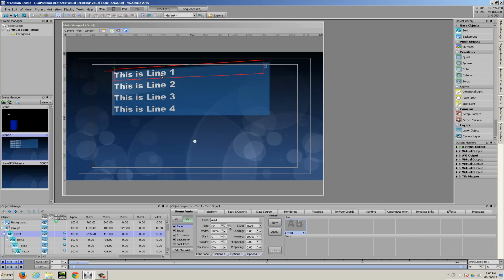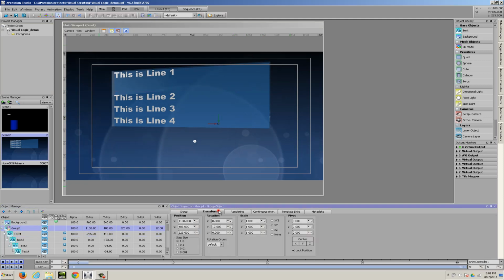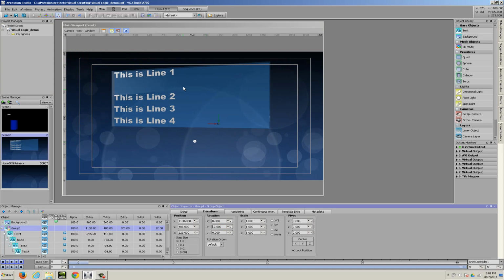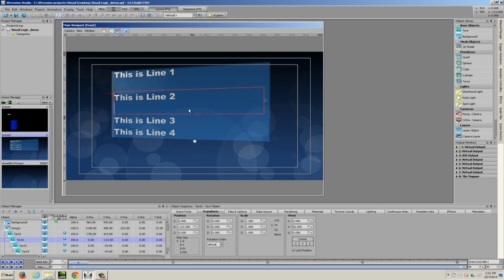for traditional multi-line templates. So you'll notice that when I insert a line break, line 2 drops, so does line 3 and 4. And our background object, which is a cube in this case, so we'll just rotate this around. You'll see that we've got this reflective cube with our text on it. It's also changing its Y scale in relation to the bounding box height of that text object. And you can do this for each line. So as I add line breaks to the second line of text, we drop line 3 and 4, and we increase the scale of the background object.